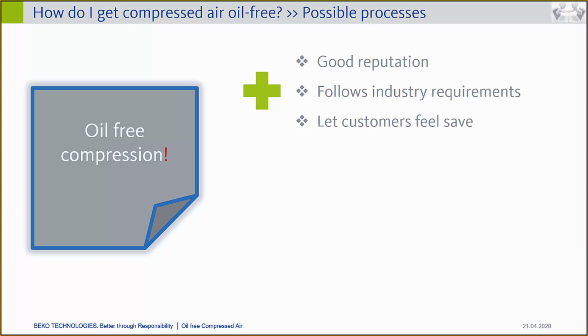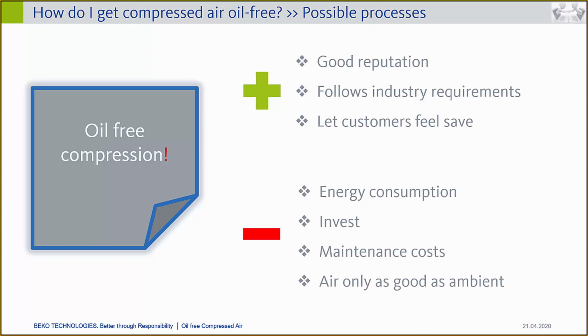And it lets customers feel safe, because there is no risk of oil breakthrough, but there is still some oil which enters the compressed air system, which we have seen already in the slides before. So it still requires some kind of air treatment system.